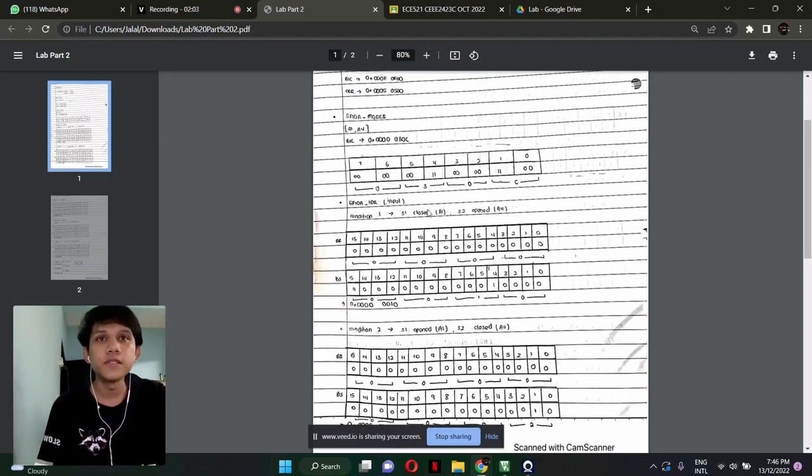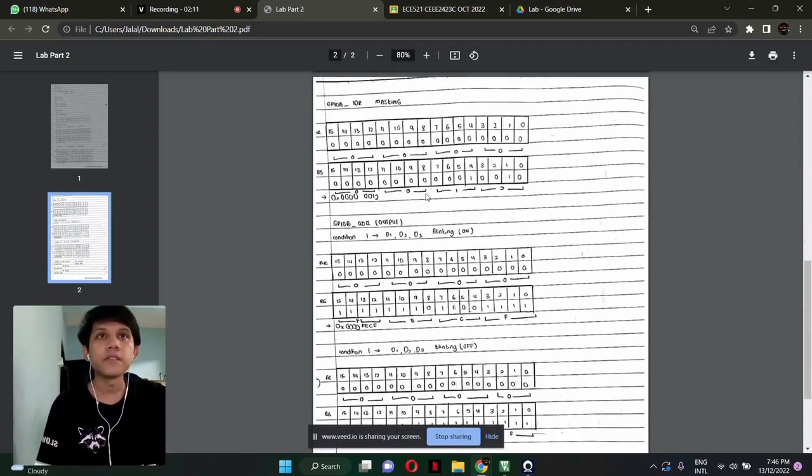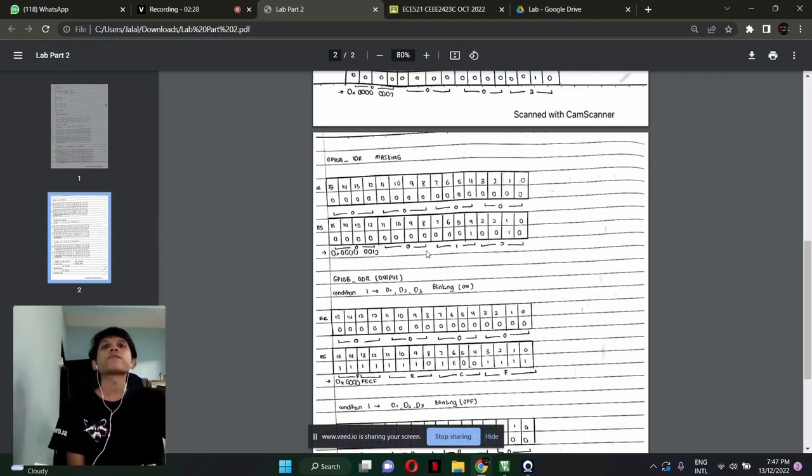Before we proceed, we need to do the masking first, because we only do masking for the input. As you can see, we use two switches, and we need to enable the switches at port A1 and port A4. We put logic 1 here, and it becomes 0x00000012.